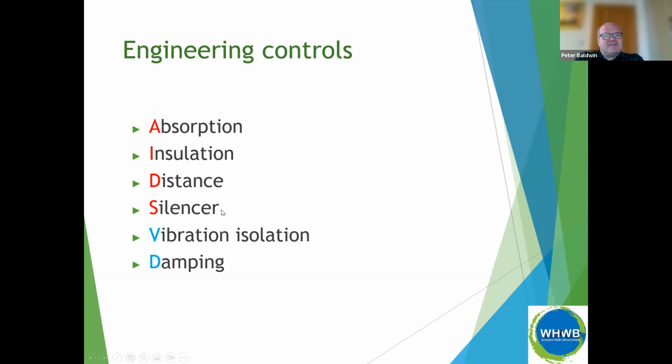Then fit silencers. If you've got pneumatic systems, when they expel air, they can be quite noisy, so you can put a silencer on them. Think about a car: the exhaust has a silencer on it, and cars are generally quite quiet, but if there's a hole in that silencer, or it's fallen off for whatever reason, the engine can be very, very noisy. And the same is true with noise sources. Putting on these silencers can be quite an effective way of doing it.